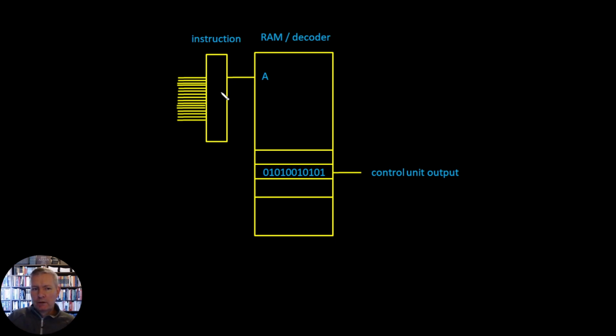As it stands now, this instruction goes into a hardwired control unit with wires running everywhere. The final output is just a bunch of zeros and ones which go to the sets and the enables of the registers, and head off to the outside world in the form of the RAM enable and set, and also the choice for the function within the ALU.